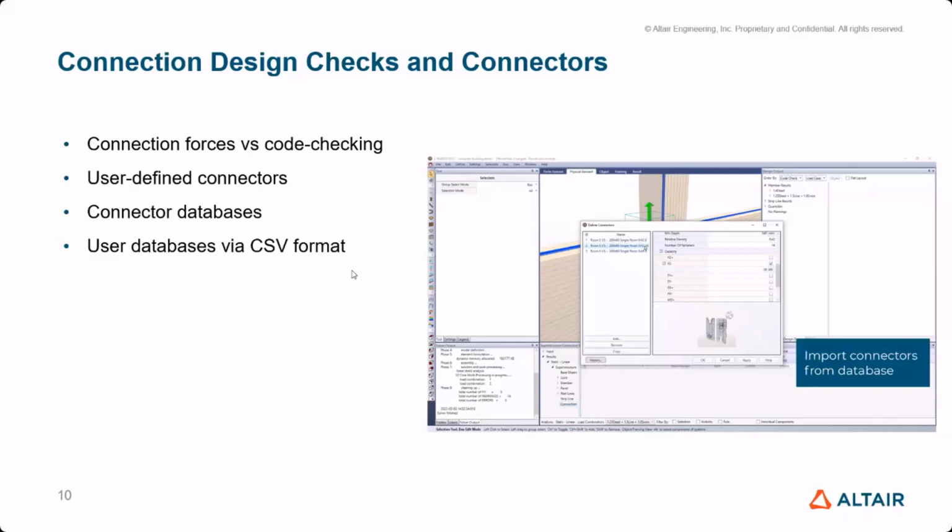Another question that came up was related to diaphragms, and I see another question actually in the chat related to that as well. And whether or not you can define diaphragms as rigid or flexible diaphragms or semi-rigid. All of them exist, just like in S-frame if you're familiar with S-frame. The example that I chose, I'm trying to recall, I believe it was using a semi-rigid diaphragm approach where we meshed it, but rigid diaphragms would work as well. So it really depends on your specific scenario and what you've defined that as.